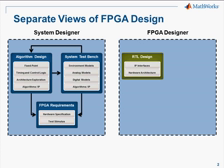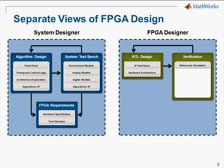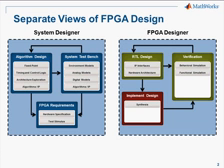This all tends to get handed off to the FPGA designer, who's starting off often with an RTL design flow, is concerned with integrating the new algorithm with other IP, with memories, with other I/O, and so on. They are generally doing that RTL development, then running behavioral simulation to start off their functional verification process. They'll go ahead, do synthesis to get some initial assessment of the resources that will be required to implement the design. Then they can proceed with the remainder of the implementation process, get more detailed timing information on the design, and iterate here to improve the resulting implementation to get higher frequency and to drive down the resource utilization.